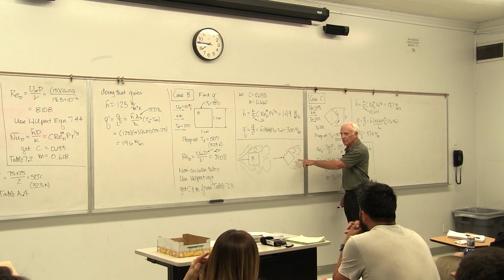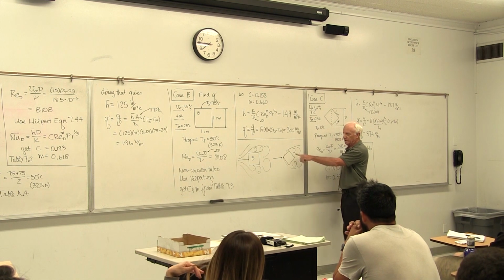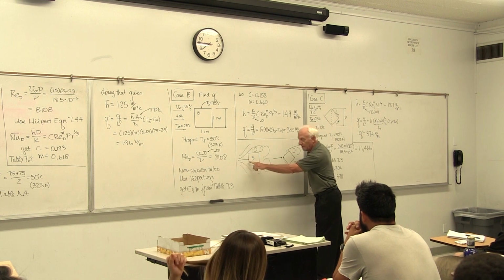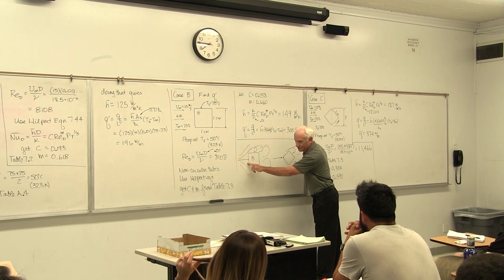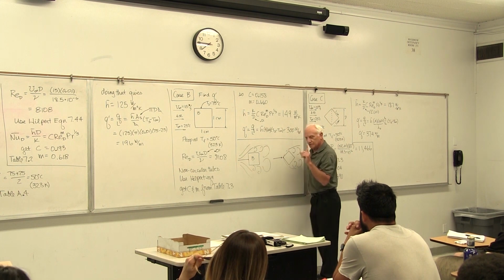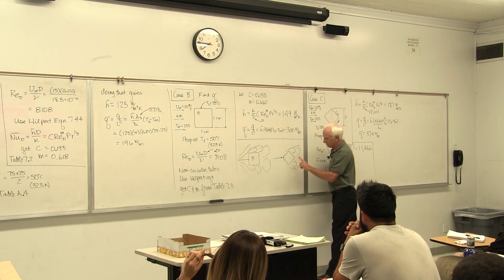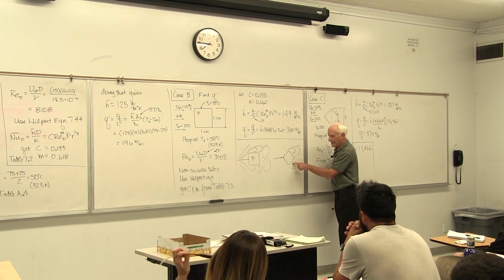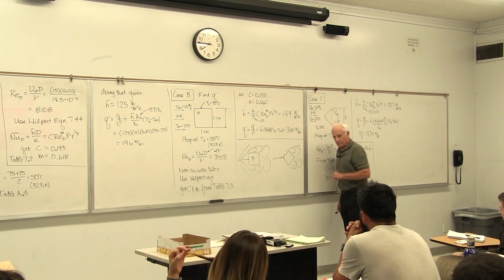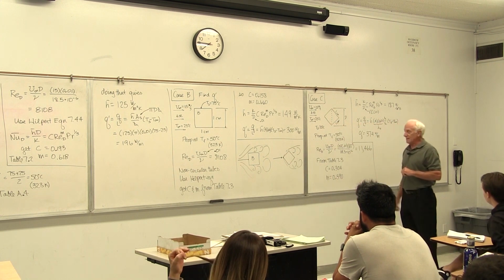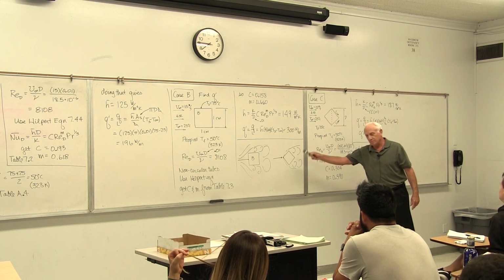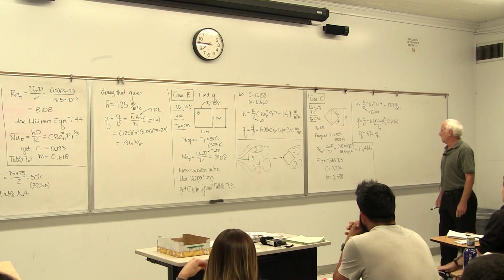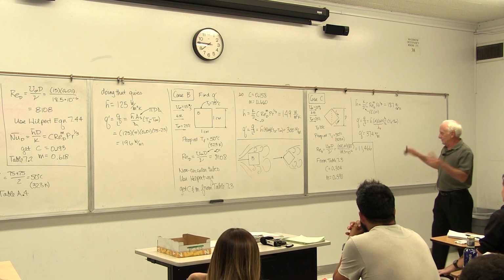This guy here, look how small the wake region is. Look how big the wake region is. The front of this guy here has really good heat transfer, but that's only one surface out of 4. Look at this one. 2 out of 4 have bad, 2 out of 4 have pretty good heat transfer. So that's why this guy wins right here, explained by fluid mechanics. Okay, big long story, but just so you know.